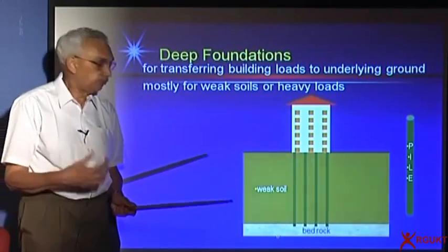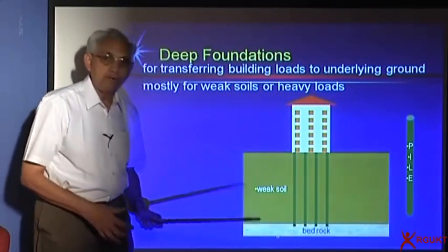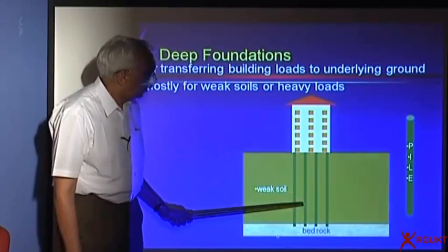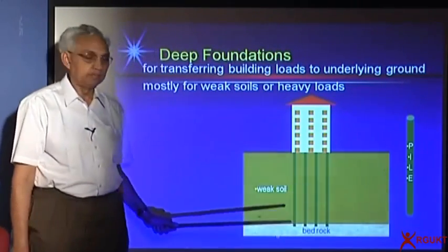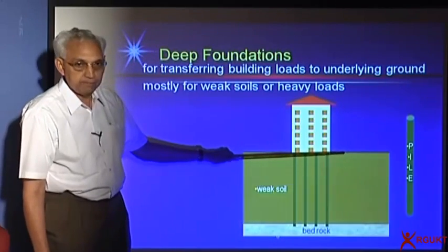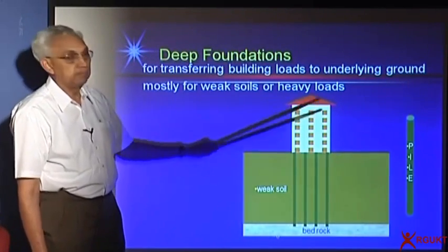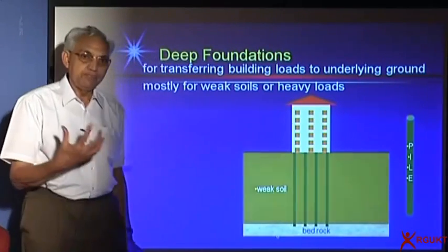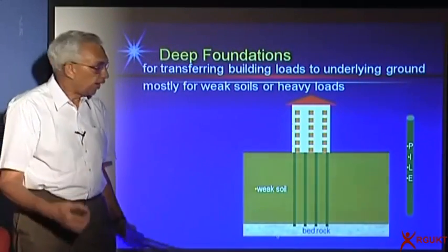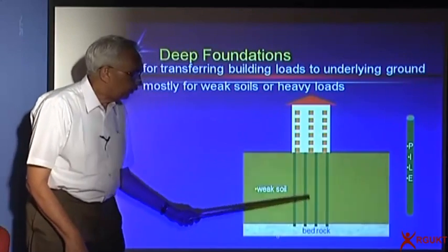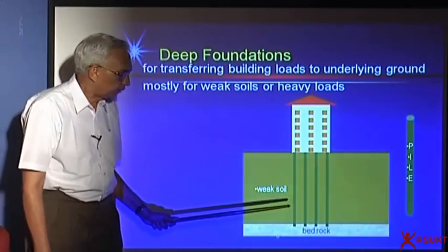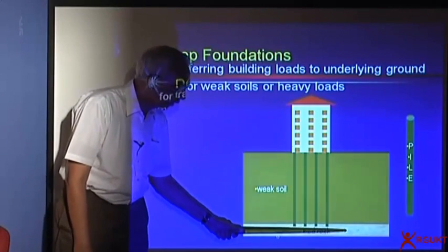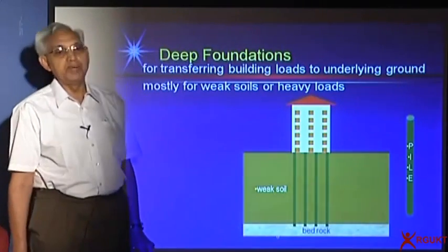So what we do is we try to drive the piles or excavate a hole, fill it with concrete and reinforcement, and then I'll get the pile foundations. Then of course we do provide a raft or a pile cap here. On top of it we provide the building. So please remember, if the loads are heavy and the soil is weak, you need to go for deep foundations. And please remember, this soil has to be characterized as well, also the soil at the bearing level.